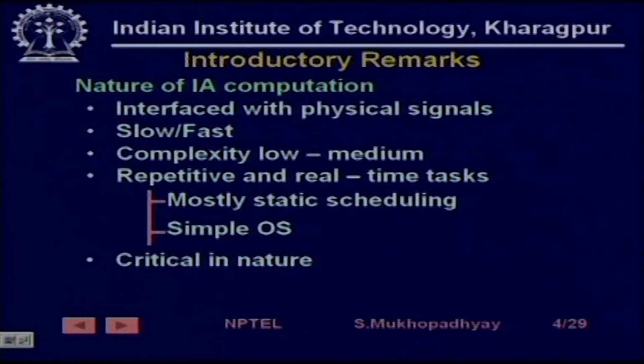Apart from that, one thing is very interesting: when you have a PLC, these computational tasks are very mission critical in nature, in the sense that we do not want any kind of errors in them. So, they should have very good reliability and they should always ensure worst case performance specifications. We cannot rely on average case performance specifications.